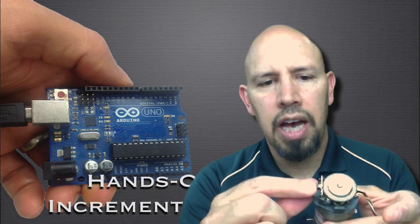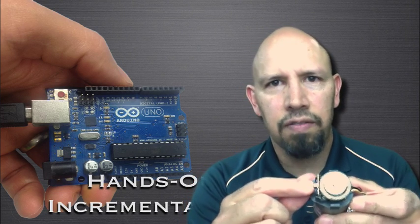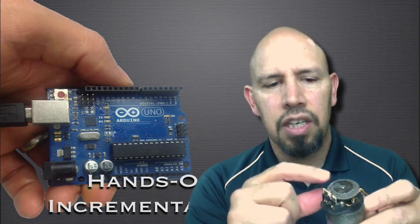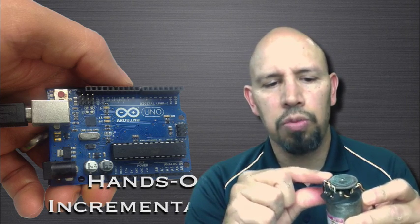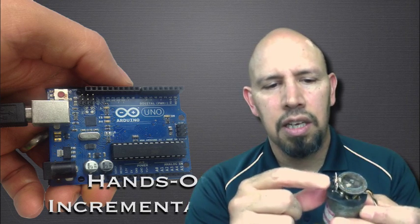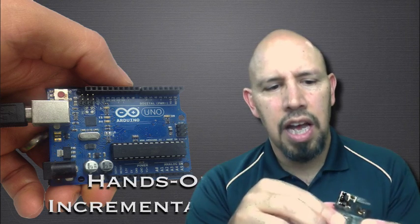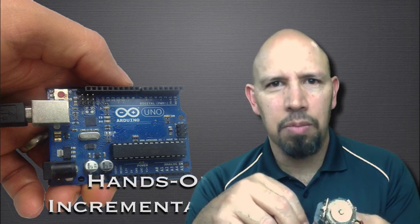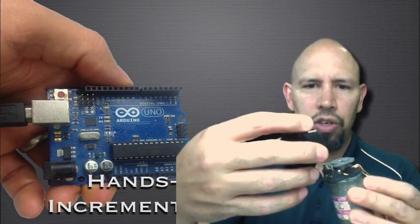And over here we have a Hall effect sensor, and the Hall effect sensor can pick up magnetic variations. As each tooth goes by this Hall effect sensor, it picks that up, and it then has additional circuitry in here that converts that signal into a nice square wave. Actually, it does the square wave in quadrature. We talked a little bit about quadrature last time, and so that's what this is. This is a magnetic encoder.